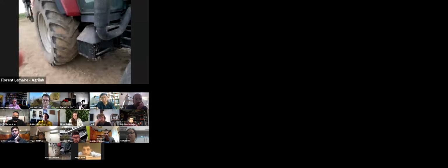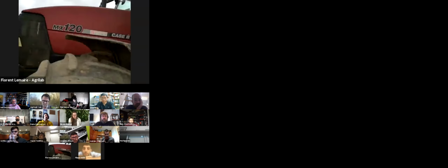So you can see I'm in the field. We are very weather dependent. It's not sunny today. On the tractor we have a steering angle sensor to check where the wheels are going, because in some tractors with a hydraulic steering system, the steering wheel drifts a little, and you don't have a direct connection between the steering wheel and the wheels. So the middle position of the steering wheel is not always the same. So we need a sensor directly on the wheels to know the correct angle. We have here the GNSS receiver, a dual channel receiver to receive the position from the satellite.